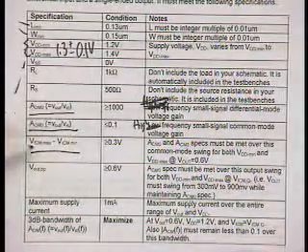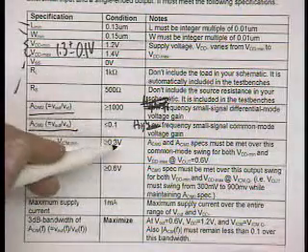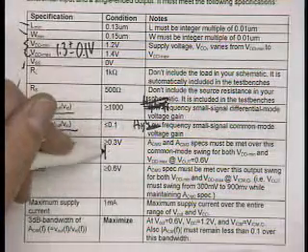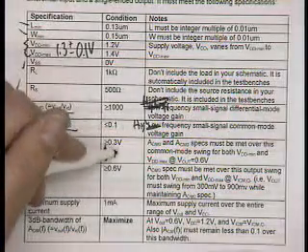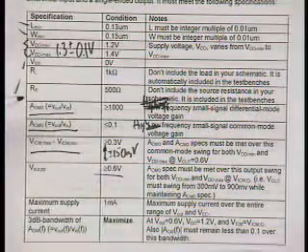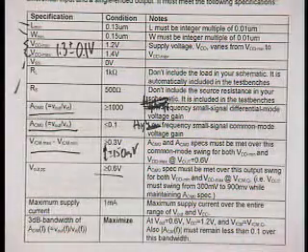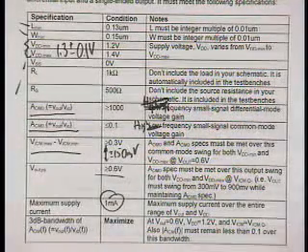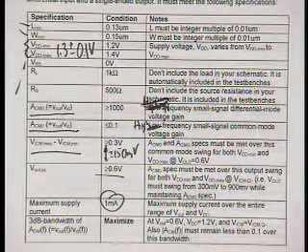All right, the input common mode is basically what you specify, and it's going to go up and down plus or minus 150 millivolts. The output swing is as before, and now instead of having an FOM that is a product of your area and your power consumption, we're setting the supply current to be equal to the maximum current you're allowed to dissipate, which is 1 milliamp.